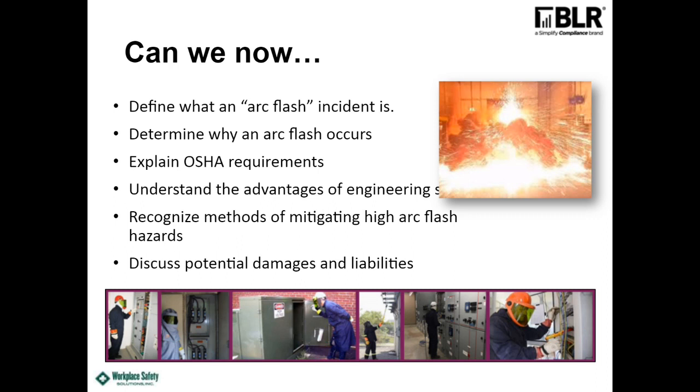So OSHA, we talked about, so in 269, the utility standard, there's a little bit of arc flash data in there, but quite a bit actually, but it only is related to utilities and utility-like work, so it's more like medium voltage stuff. In Subpart S, they have not yet updated that to match up with the most recent NFPA 70E. I expect that's going to come down the pike probably within 5 years or something, I'm hoping, but we'll see how that goes.